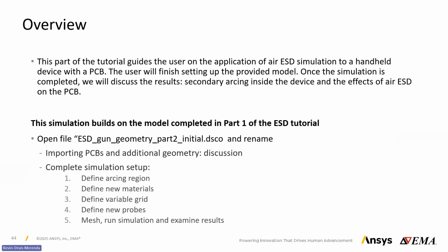So we're going to run an air ESD simulation on this PCB that we just saw. It's enclosed inside an enclosure that is metal, and it is set up in a location that is just under the ESD gun, and that enclosure is actually on a test bench that is grounded. And we'll be able to see where the ESD happens, and this is one of our tutorials.